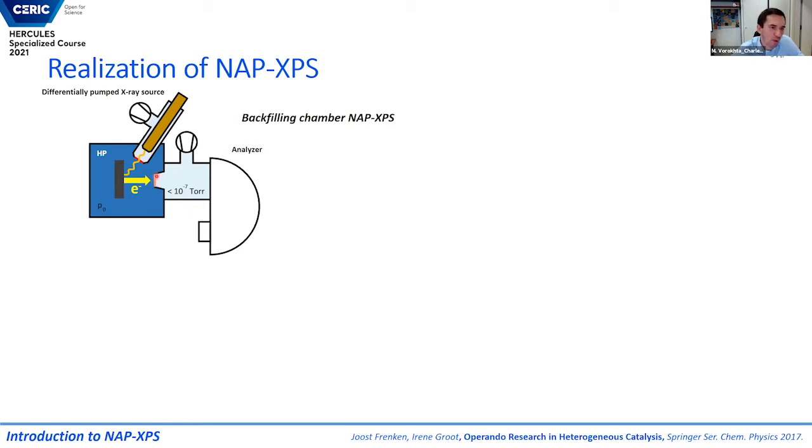So if you want to have penetration of electrons through such a membrane, you need to have it as thin as maybe 10 nanometers or even lower. And of course, such a thin membrane is usually very, very weak. It is very difficult to have it stable, to protect it from high pressure. You cannot increase the pressure too much. You can go only to relatively low pressures. And as I said, it is dangerous because it can break at any moment.